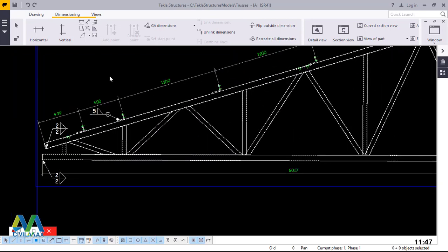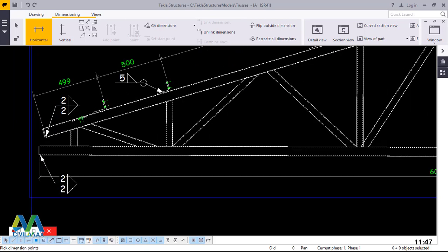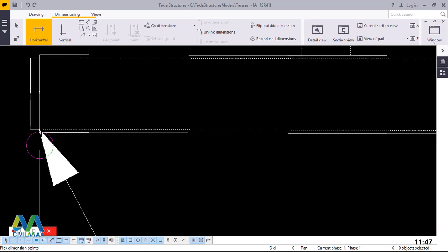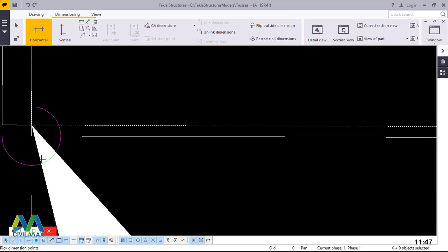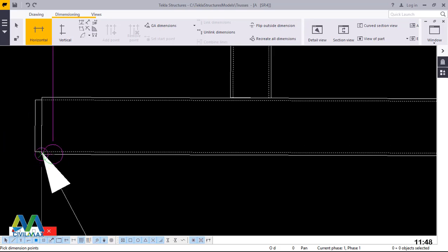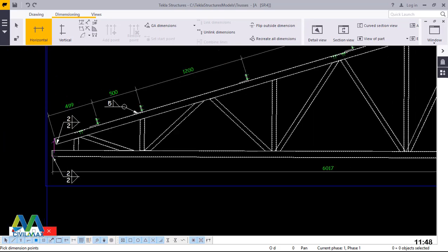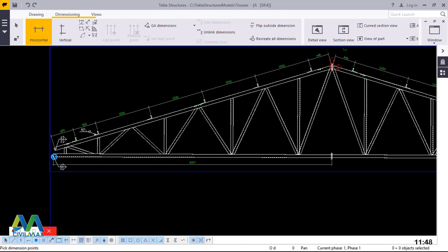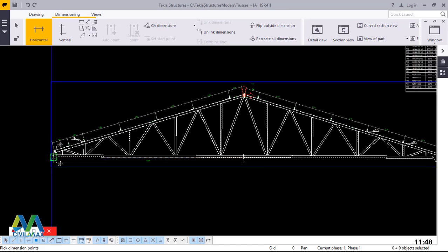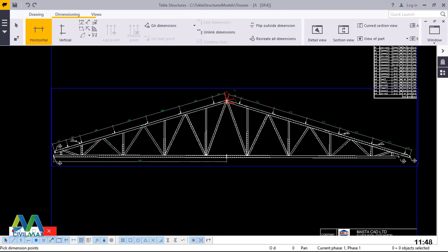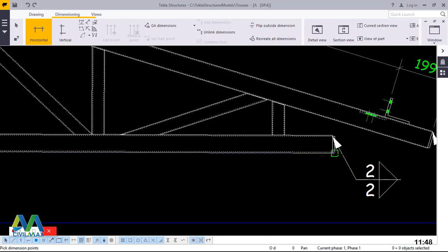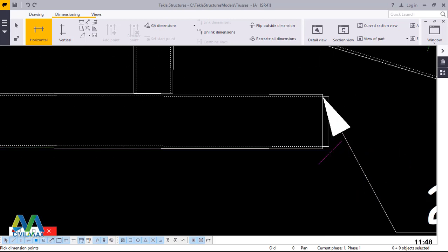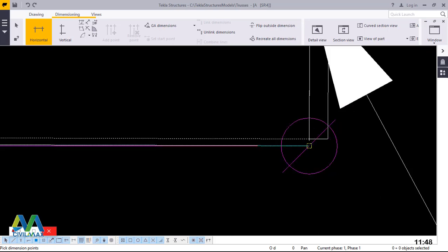Then once again I'll go back and click on that, then snap at the far end here, right at that corner, and then move out. I'll move out to the far end and get to the total length of our truss. This is the point I'm targeting. Let me just mouse over that and zoom out, and I'll snap right there.